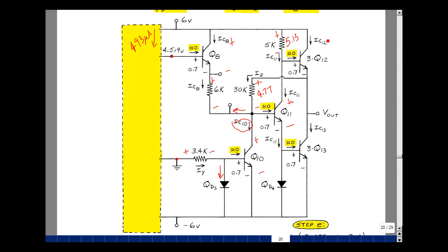And for transistor 12, we've got this node voltage here, which is 6, and then the output voltage we found was 170 millivolts. The difference of those two is 5.83 volts. In other words, about half the power supply is here and half the power supply is here, if this was 0 volts. Then lastly, for transistor 13, this node voltage is 0.17 volts, and then this node voltage is minus 6, so the difference of those is 6.17.